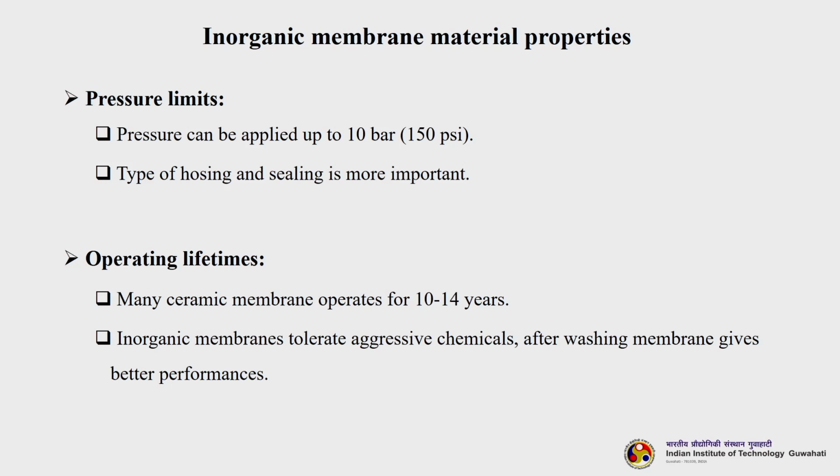Many ceramic membranes actually operate for 10 to 14 years, which is a pretty long time. You cannot imagine this for any polymeric membrane. Whatever polymeric membrane you can talk of, no polymeric membrane will give such a long lifetime. And inorganic membranes tolerate aggressive chemicals, after washing the membrane gives better performance.